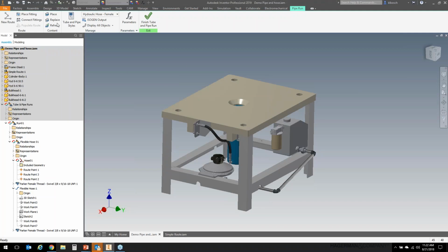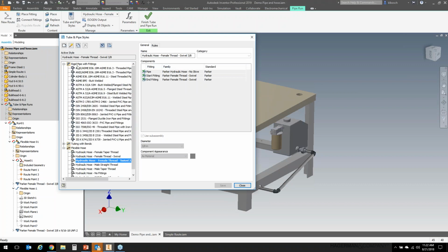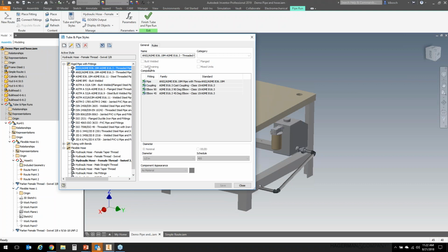Certainly, and I see John is talking about the sloped pipe runs. That is simply this setting, I do believe, and Mark, correct me if I'm wrong, this self-draining setting here. So if we were to go to edit that, we would simply click the self-draining setting, and that creates those gravity-fed runs. Yep.